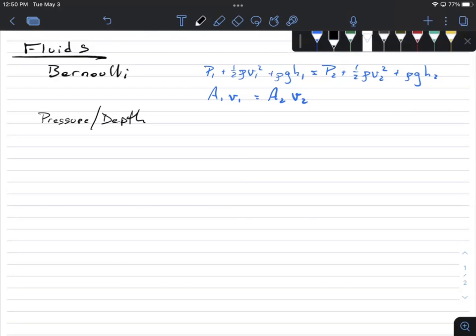And so the equation that tells us how much pressure you would feel is P is equal to rho, that's the density of the fluid, because of course, what type of fluid you're in matters to how much pressure you'll feel. A thicker fluid, let's say water, is going to push on you a lot more than something like air, which is thinner. So it should depend on the density of the fluid times g, which is just 9.8, times h, which is how far down did you go. The further down, the more pressure you feel.